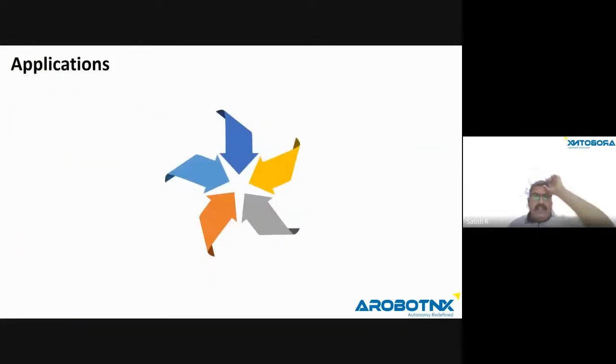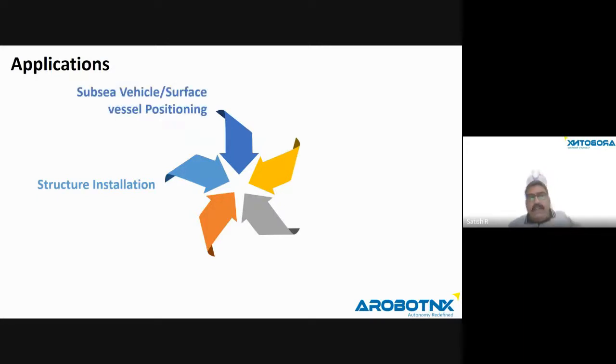Now we shall jump into the applications, like structure installation, subsea vehicle and surface vessel positioning, subsea metrology, subsea asset monitoring, and pipeline installation. But I'm not limiting it to that. We can also deploy Sparse LBL on hydrography, multi-beam jobs, and pipeline cabling. So many things. It's getting expanded in many deployments because it's going to be quicker. It's not going to take time. And the second biggest advantage is that you carry out everything in the subsea itself.